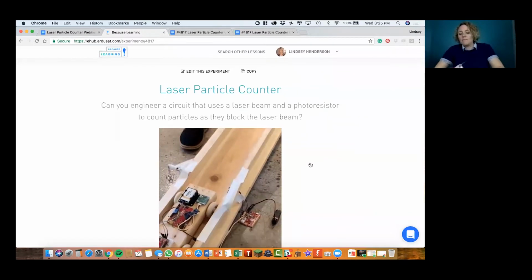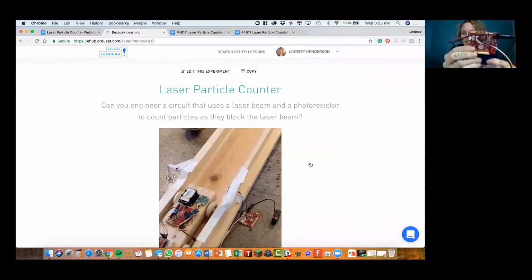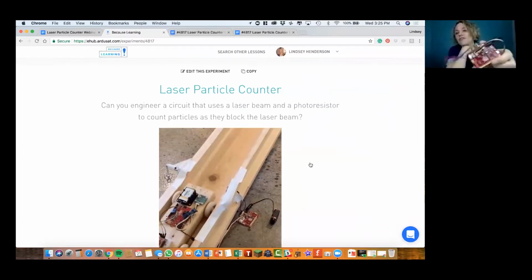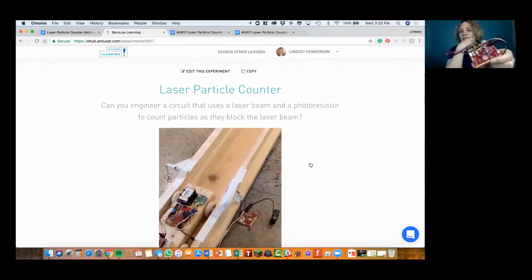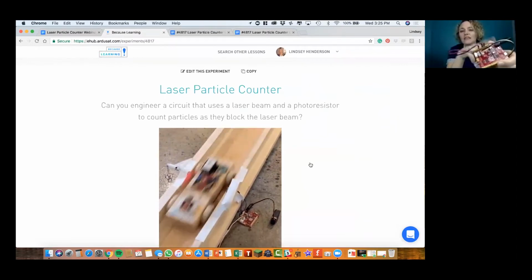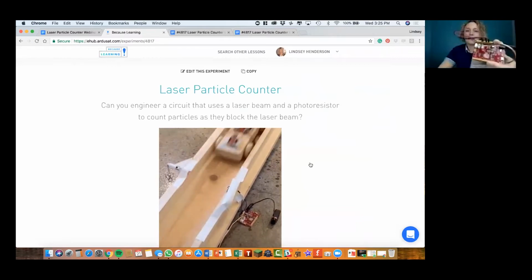Another common problem is that the labels on the Arduino are really small, and you have to count down the number and be careful about the grooves and how you stick them in. Sometimes students will just willy-nilly put them in wherever, or it's off by 1, and it makes a huge difference in your circuit. So those are great things to check.